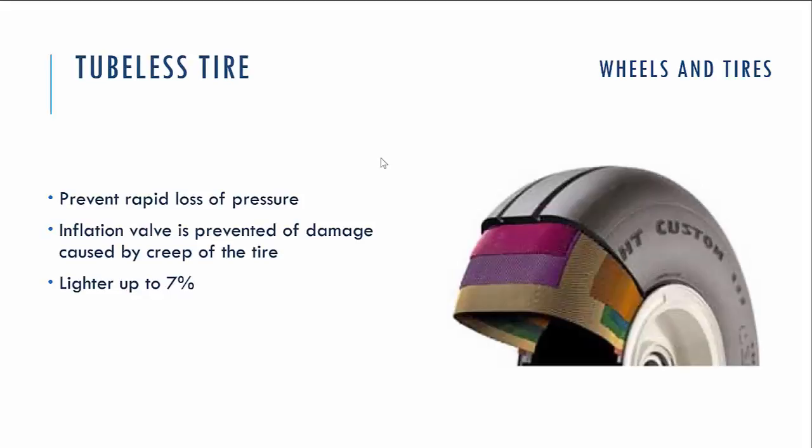But for tubeless tires everything is better. It's lighter because of the lack of the inner tube, and also the inflation valve is placed on the hub of the wheel separately from the tire, so creeping of the tire will not cause any problem at all.